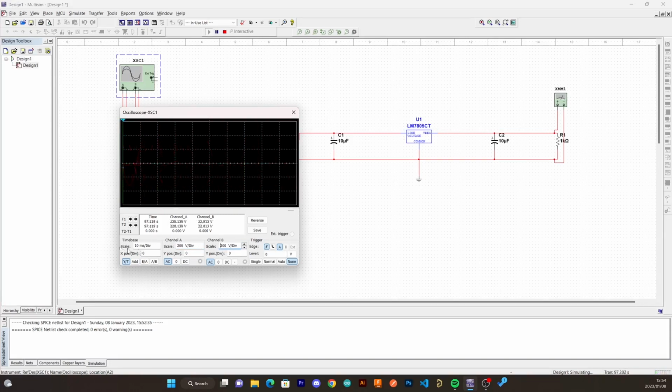So you can actually appreciate that we do have something going on here. What we need to do is adjust the scale so that we can see our image in real time. If you take a look here at the voltage, they are on the same scale, and if we switch off channel B by pressing this 0, you can see that our channel A is bigger than channel B. In this case, it shows that our transformer is working and that it stepped down the voltage.